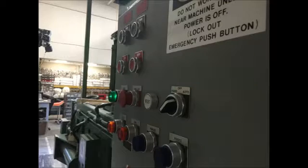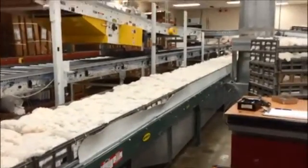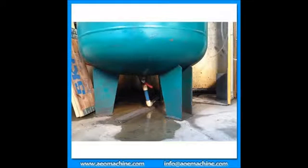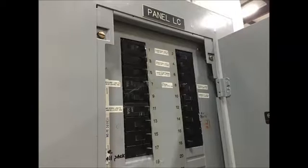Stored power is also a concern when working on electrical, compressed air, or hydraulic equipment. If stored energy is not safely released, the equipment has the same potential for movement or electrical shock, even though the power source has been removed. The removal of stored energy is typically done by bleeding the compressed air or hydraulic fluid in the system. Contact with the areas of electrical stored energy, such as capacitors, should be avoided since the shock hazard has not been removed. You must check with the equipment manufacturer to ensure that you have properly removed the stored energy.